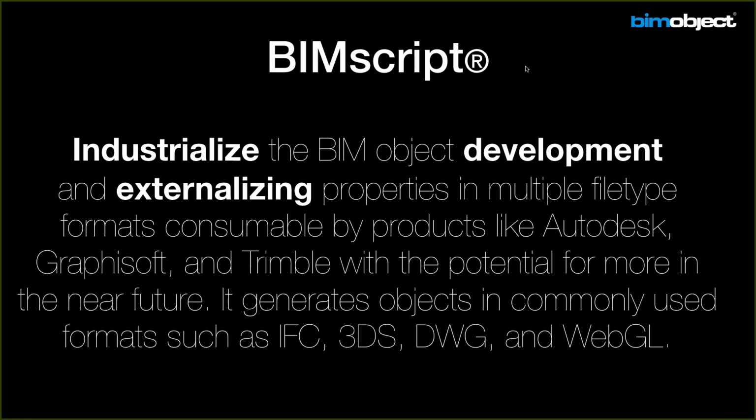So how do we get all that content built? Well, one way is we have a proprietary BIM script language, and it allows us, and you or whoever, to industrialize how this content is developed. It allows us to create simultaneously numerous outputs out of a single digital model, a single solid model, into Revit, ArchiCAD, SketchUp, IFC formats, 3ds, DWGs, WebGL, which is a very big 3D that anybody can see on the web with a viewer.